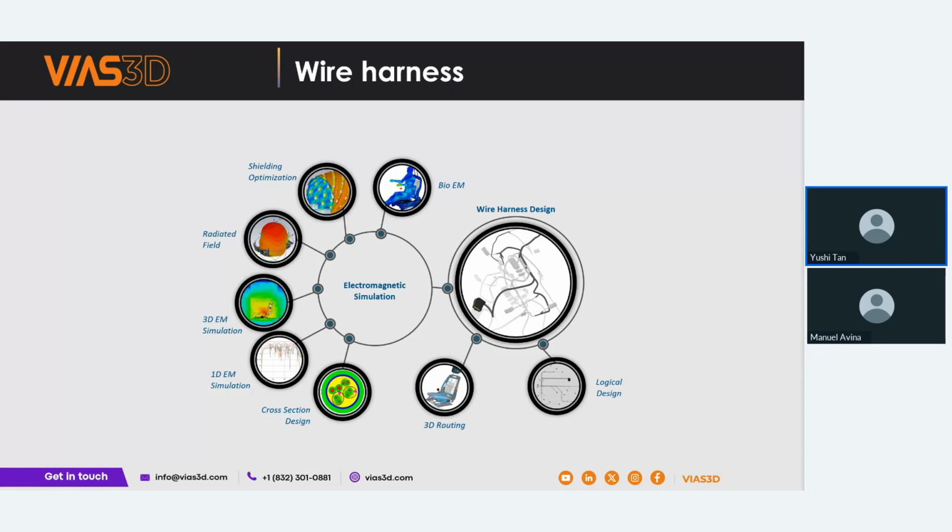As an example, unshielded twisted pairs can easily introduce common mode currents when the pair is not perfectly matched. It can happen in the excitation and also in the middle of the twisted pair itself due to, let's say, kinks and bends. So it's going to be reflected in the S parameter when you perform the simulation. This common mode current can then introduce radiation from the cabling system to potentially affect other parts of the system.